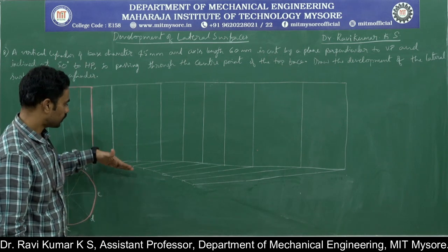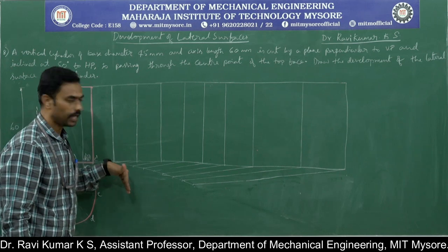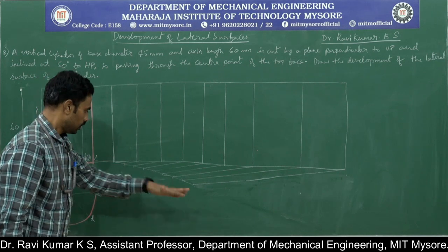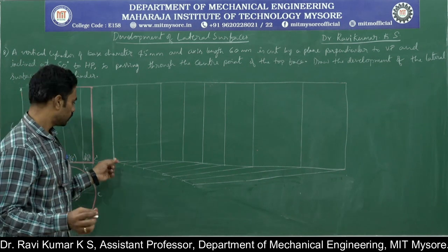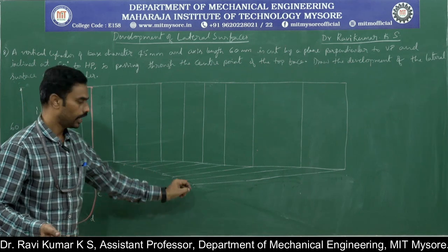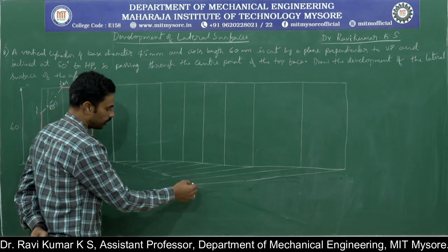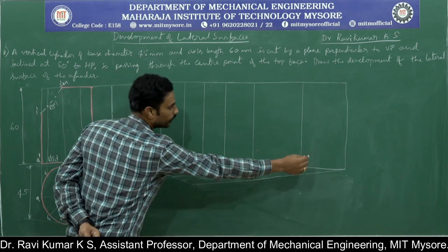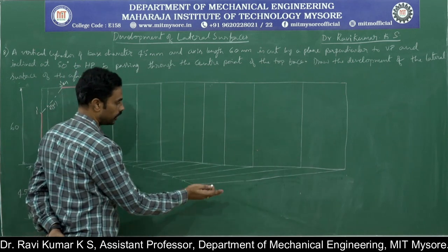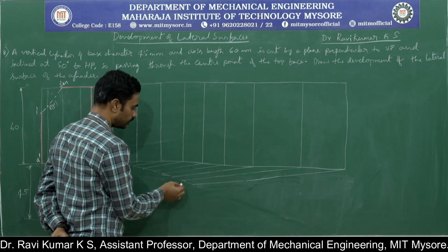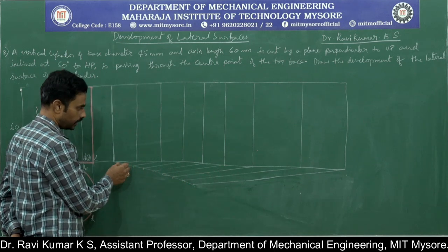Okay? I will just explain once again. Take any acute angle and take your compass, take any division, cut 8 divisions. Then from the end, you just join the end with that particular end. And keep on drawing parallel lines with these division lines.